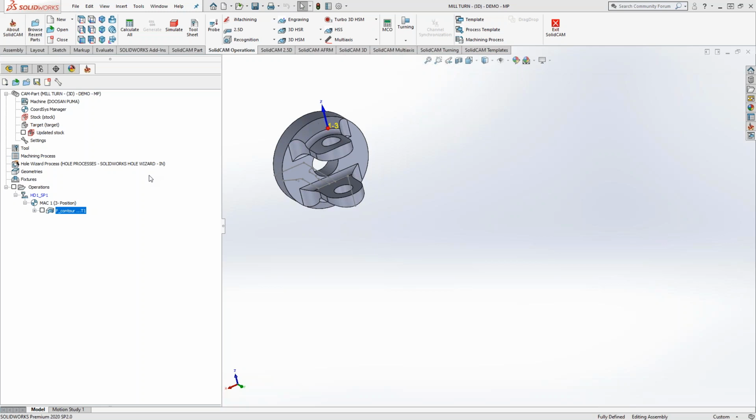Yeah, and one thing that I have noticed, if you can't find a material on matweb.com, sometimes there is a different name for it. In your mind, we always call it a certain name, we'll just go off 1018. We always call it 1018 cold rolled steel, but in maybe other places they call it a different style name or something like that. So you may just have to look up that as well.